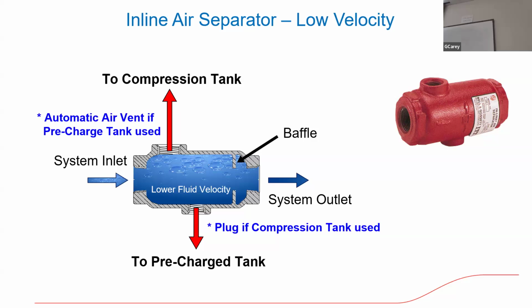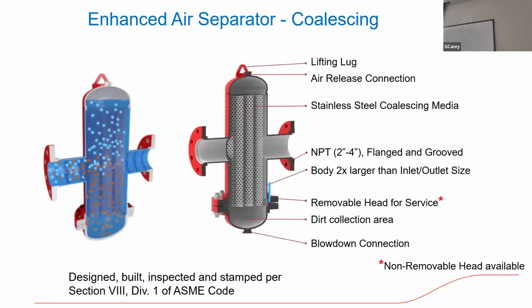So it's just velocity. And it's so simple looking, but there actually was engineering involved to say, hey, this diameter right here will cause this 5 feet per second to slow down to half a foot per second intentionally. And then continue back on the way back out, back down to our 4 to 5 feet per second with a smaller diameter pipe.